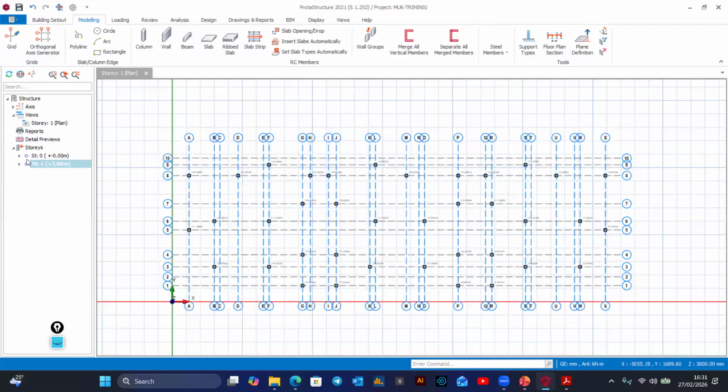Now, let's focus on stories. We have a structure which is a 5-storied structure. When you are starting the project, this is the only important structure. It assumes that you're already on first floor. That's why when you look here, story 0 is the foundation. Then story 1, first floor level. That's why here it is 3 meters.